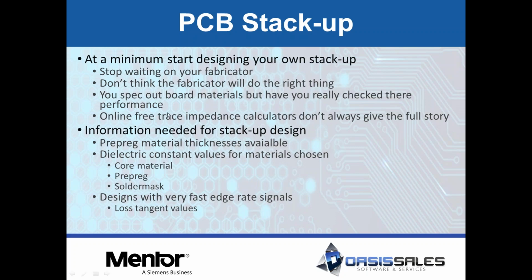You spec out different basic material, but you never know what the performance of your board is really going to be unless you check your stack-up yourself for impedance. And if you have any signals with edge rates over 5 nanoseconds, there's a good possibility you're going to have problems. And most of the ICs out there today are running with slew rates that fast.